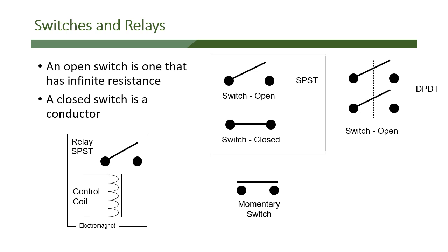And we can actually have that switch controlled by a computer or by another voltage source in a remote location, so that we can remotely control something that takes a high current flow, or control something that needs process control, where we use a computer to control it. We can use a relay to do that as well.